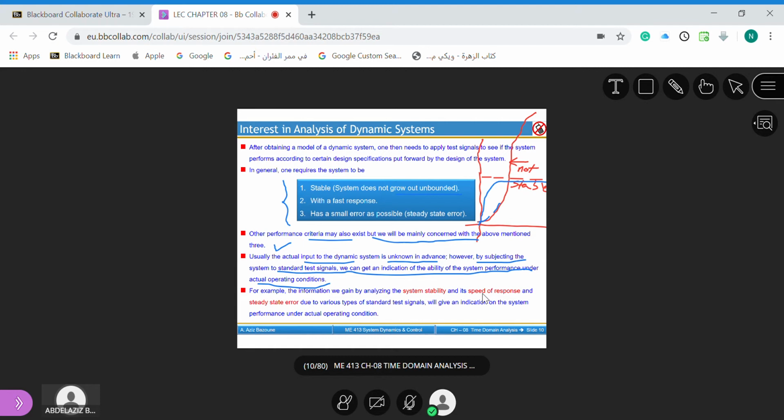If it behaves like a first order system, we say our device we bought is a first order system. Otherwise, it will behave in another order that you can characterize later on. We can also say that this is system identification, which means you identify your system, how it behaves.